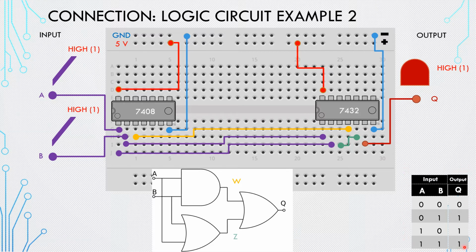Try to verify what kind of table we have. If you don't recall it, this should be OR. So rather than connecting 3 gates, you can just bring an OR gate and you're gonna have the same answer. This is what we're gonna take in the next experiment. Try to simplify a circuit in order to reduce the amount of the used logic gates.